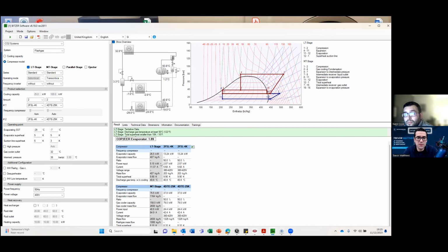And lots of people think the drives are difficult, but they're not. If you went in and understood what the compressor needs, you input the compressor information into the drive. People say, oh, there's 1,000 parameters. Yes, there is 1,000 parameters, but you don't need to change 1,000 parameters. You just need to change the specific parameters for that specific compressor. Absolutely. There are options here.